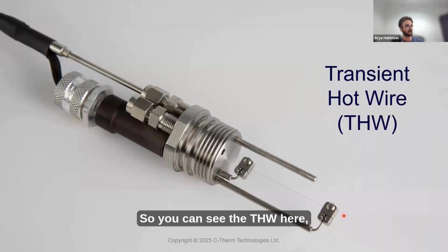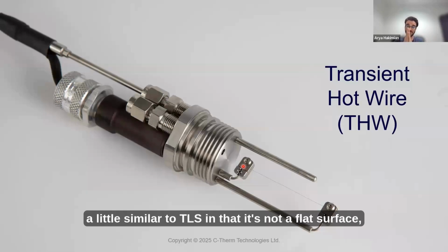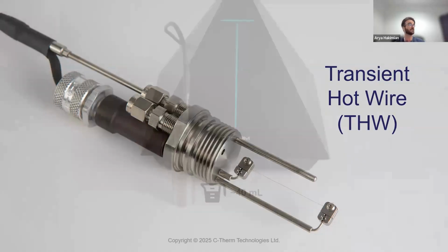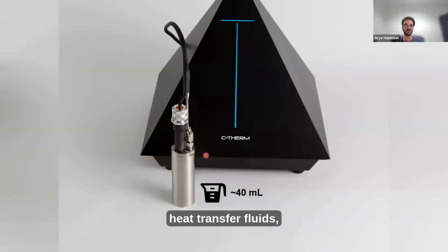So the last one on Trident is the Transient Hot Wire, THW. You can see the THW here, in a sense, a little similar to TLS in that it's not a flat surface like MTPS and TPS that are put in contact. Rather, it's along the length of the sensor here, which is the exposed platinum wire. It's very commonly used for testing of liquids. This is something the ASTM standard it conforms to is designed for, I believe, traditionally for engine coolants and heat transfer fluids. Certainly something that is still quite of interest for many groups.